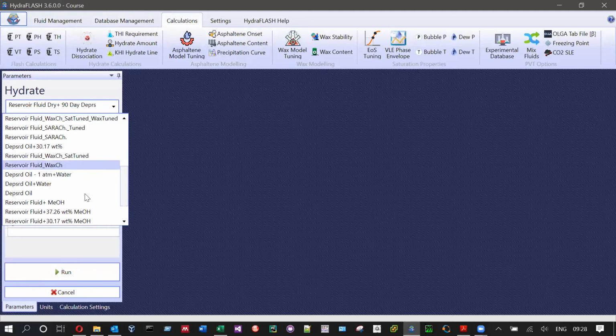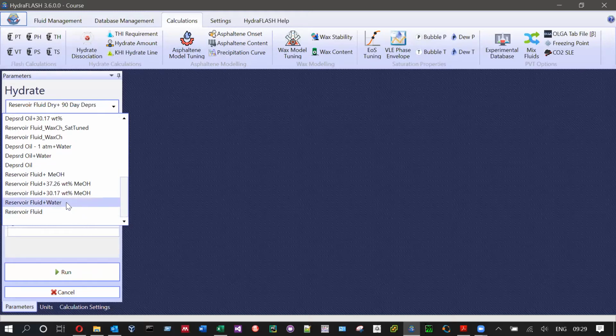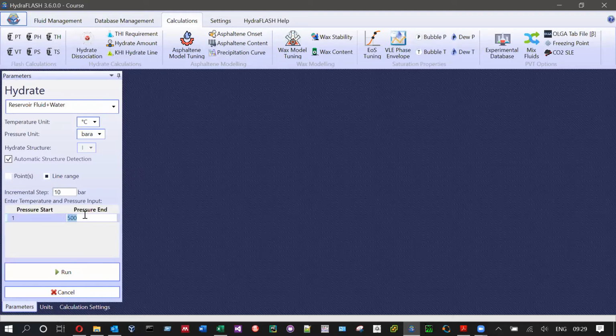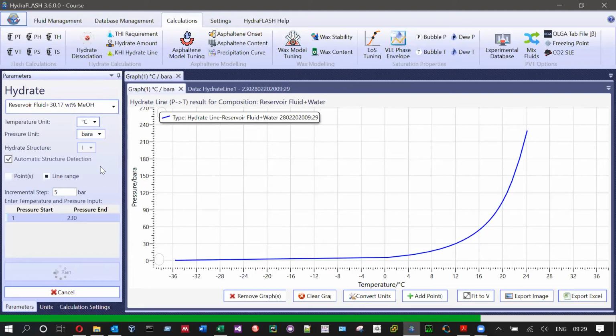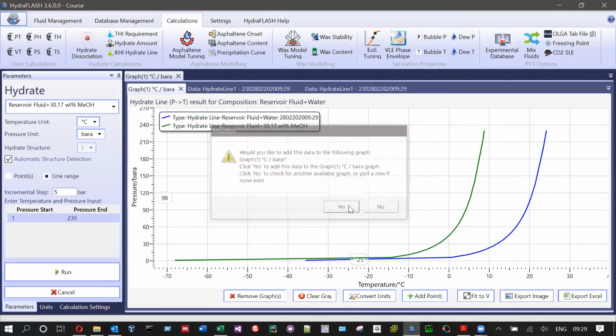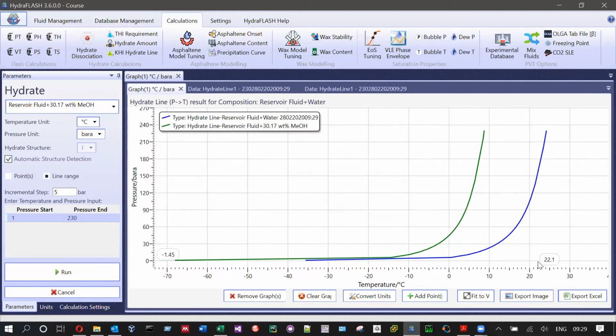So if they do depressurization and the problem is hydrate, and clearly they were sure it is hydrate because they were not sure that the pump or methanol injection is working. So they did depressurization and the blockage was not removed.